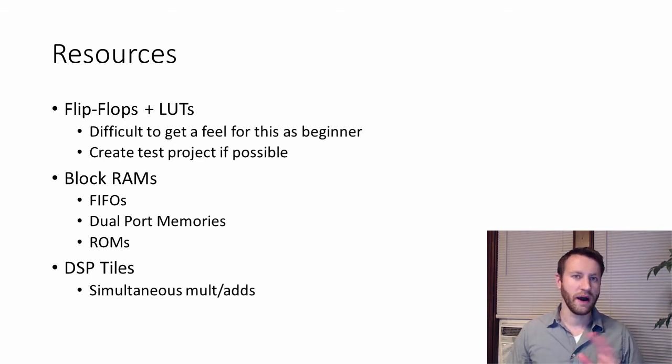If you have no idea whatsoever how many resources things are going to take, try to create a test project if possible. If you just run through synthesis by itself, it will tell you, you don't need to pin out your design, but it'll tell you how many flip-flops and how many lookup tables your VHDL or Verilog code uses for whatever design you choose.